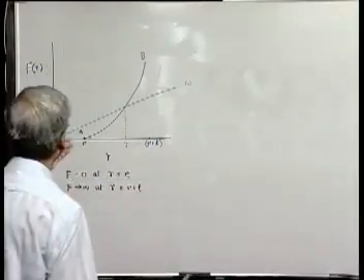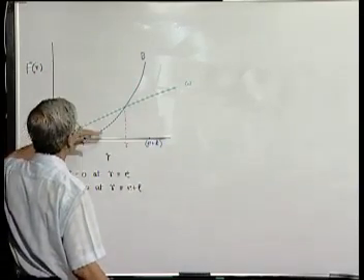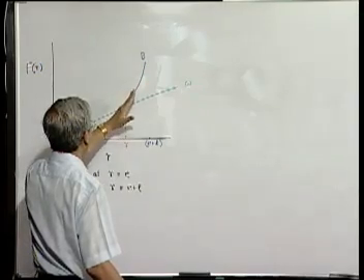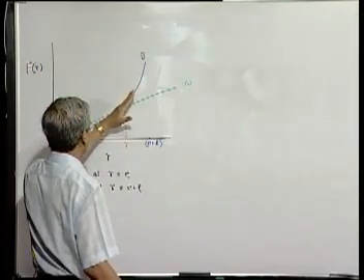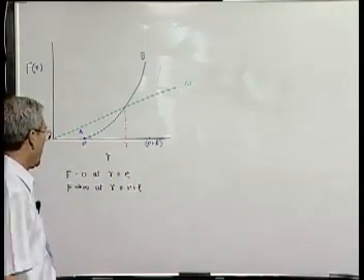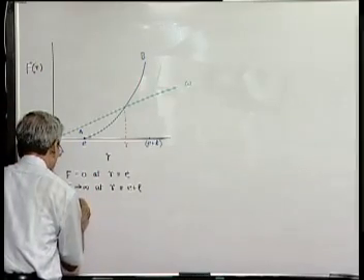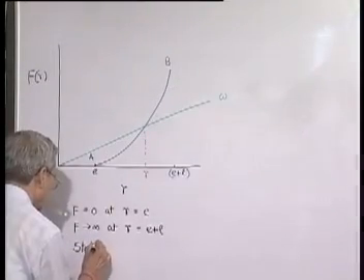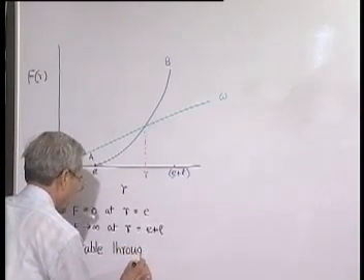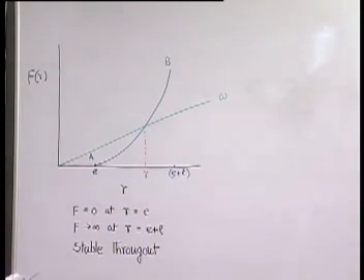And this diagram makes it very clear that whatever may be the speed of rotation of the governor, at the intersection point, that means at the equilibrium position, the slope of the control force curve is always more than the slope of the centrifugal or the deflecting force curve, and that is the condition for stability. So, it is stable throughout its range. The governor will be stable all along, we do not have to worry.